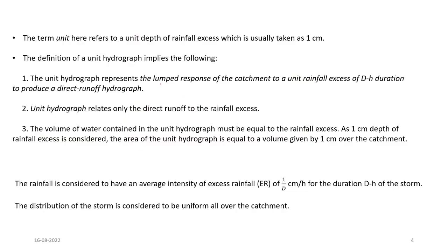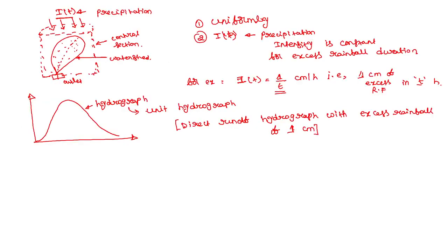And this is another way to say the unit hydrograph is nothing but a lumped response. I have already shown it here. Imagine this watershed as a linear system, and whatever the variables inside the watershed, we won't be able to consider them. We will simply assume that I_T will be converted to some function of Q_T. So whatever the input, it will be converted to output with some linear transformation. This is a little advanced, so currently you can ignore it.